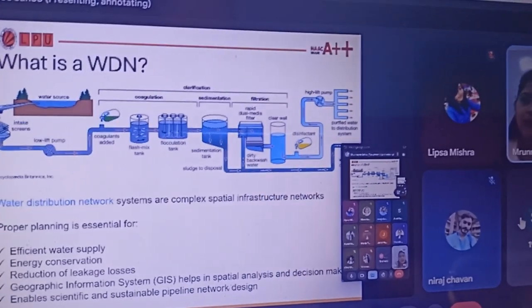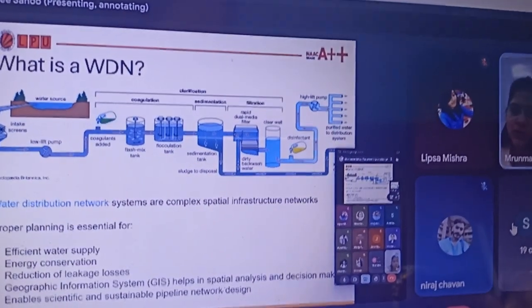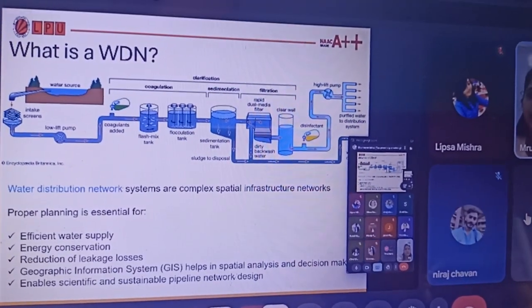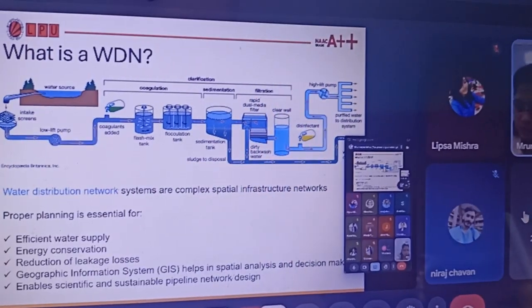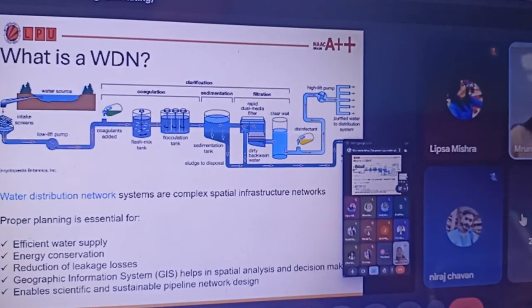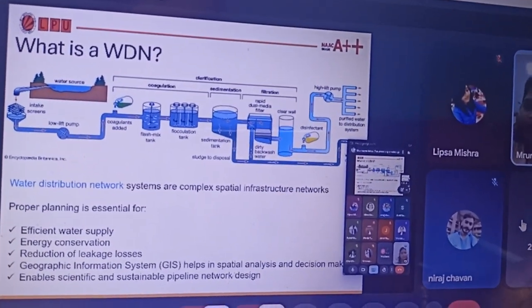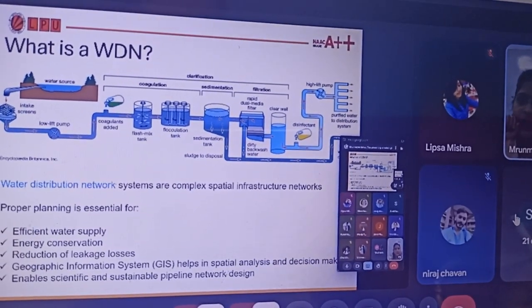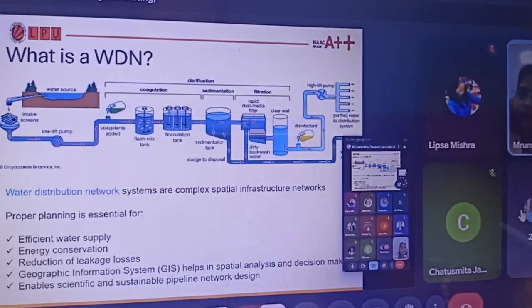from the municipality. After the water treatment plant, meaning from the reservoir, it can be groundwater or surface water. So we will pump the water from the reservoir and store it in the water treatment plant. Then we do minimum processing, like we put chlorine as a disinfectant, like we put chlorine in swimming pools. Similar to that, we put just a pinch of chlorine to gallons of water, which is measured in ppm, and that chlorine amount is considered a disinfectant.